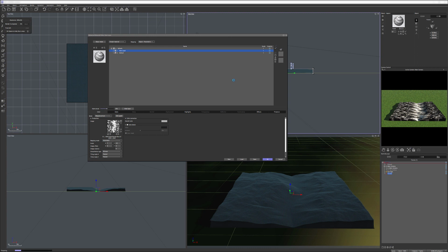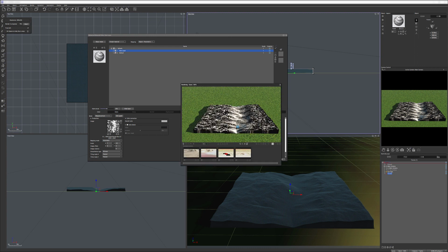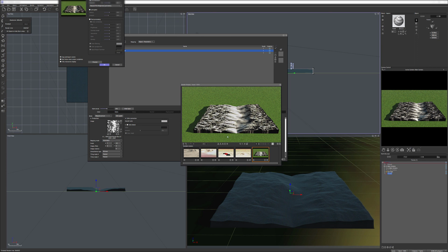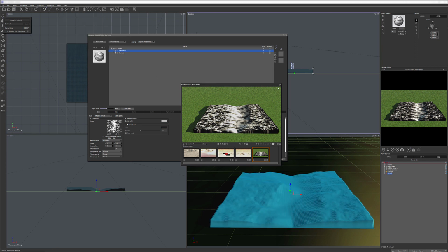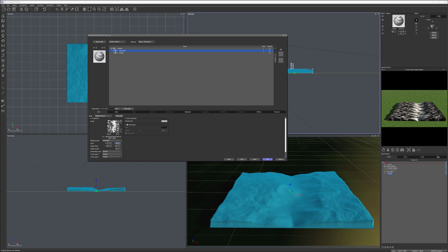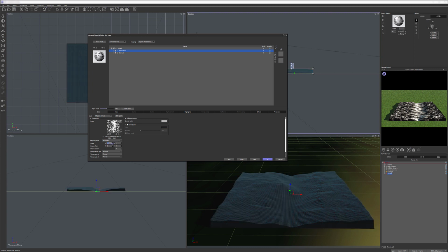Okay, let's re-render so we can preview closer. You can see how it is going on a white element. Okay, for example, let's restore Y to 1. I'll just do X maybe. Right there, and you can see, of course it's in the middle, but we start repeating on the sides. So be sure your map can be a different size, but it needs to match the proportions of your terrain if you do it with procedurals on the terrain.